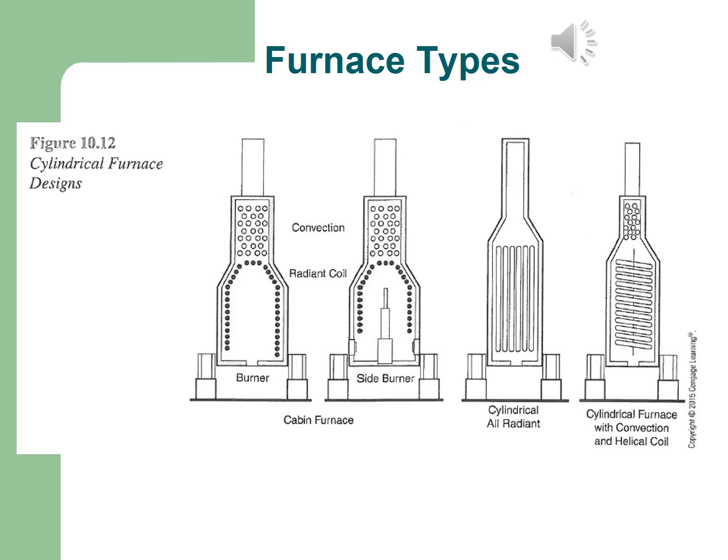Then one other thing you need to see is the radiant coils, and then you also have your convection section. Again, the radiant coils are going to get the highest temperature inside the furnace, and the convection tubes, of course, will be at a lower temperature, but again maximizing all the temperature that's available inside the furnace, so we're feeding it back again.